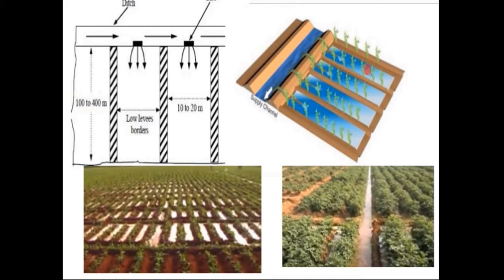The width of the strip varies from 5 to 15 meters and length varies from 60 to 100 meters for sandy loam soils, 100 to 120 meters for medium loam, and 150 to 300 meters for clay loam and clay soils. The entire land, including the rounded border ridges, is utilized for cultivation. Thus, no land is lost to production.